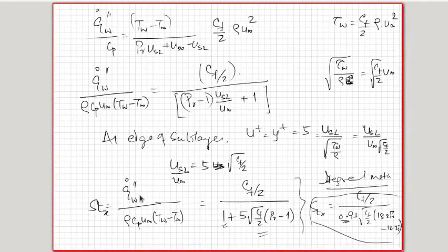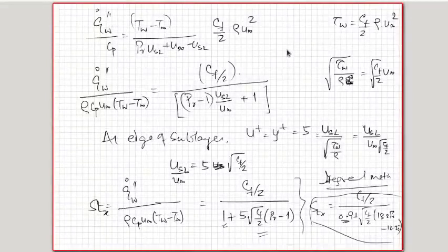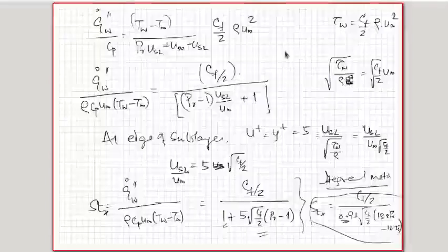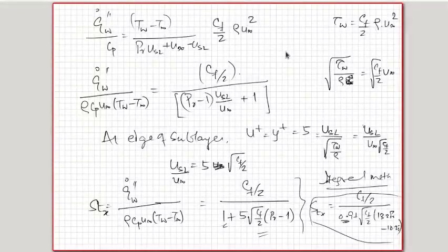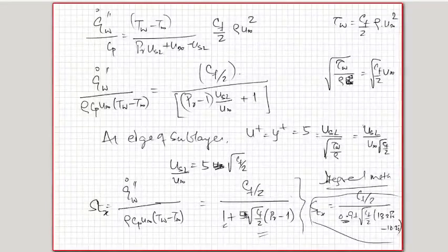This was the first formulation that was done, and it has this limitation that you have considered the same sublayer for both momentum and the energy. That may not be strictly valid when your Prandtl numbers deviate substantially from unity, particularly on the lower side. It is found that for larger Prandtl numbers there is not a problem. Similarly, there is the approximation of y plus equal to 5.